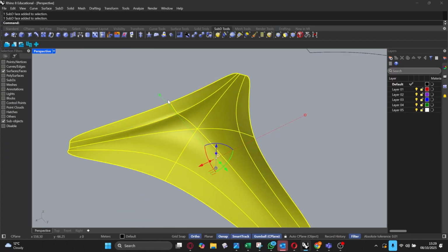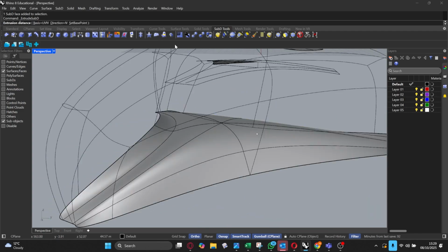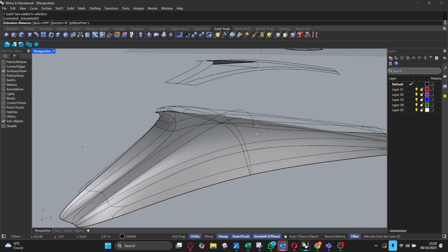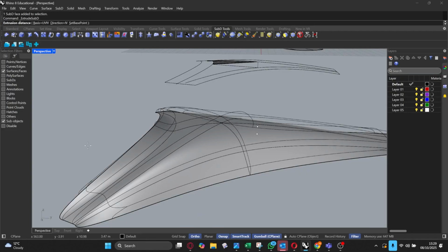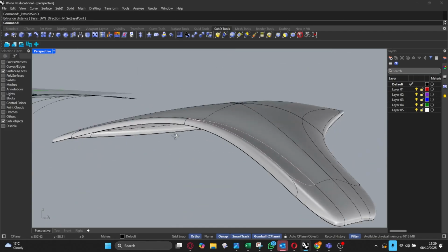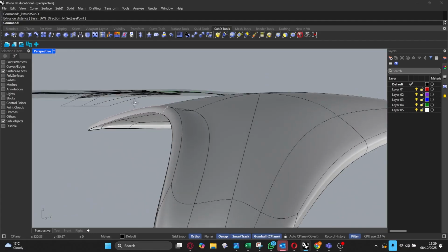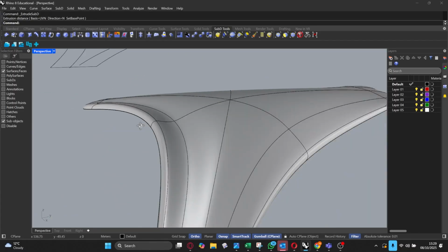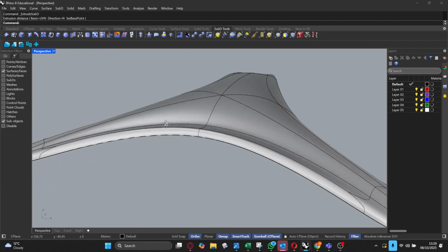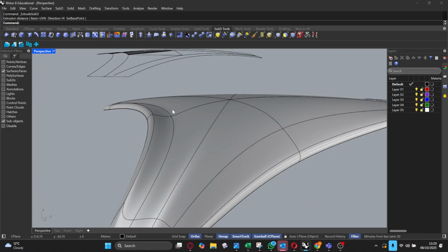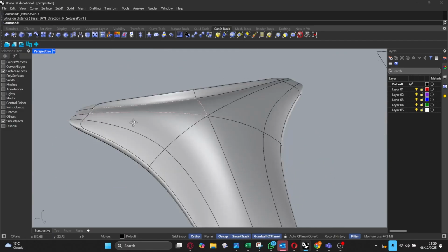for example, and if I was to extrude it, it will start to add thickness, but where it's created that rim, you see, it's introducing new geometry, but it's allowed me to maintain that curvature that I wanted. Unless, of course, I want to crease it.